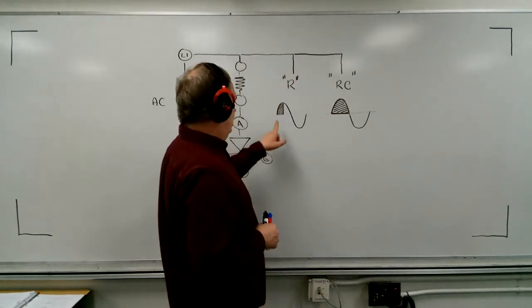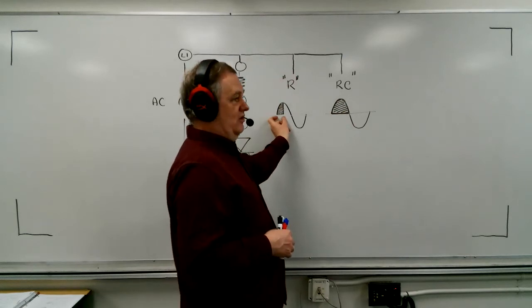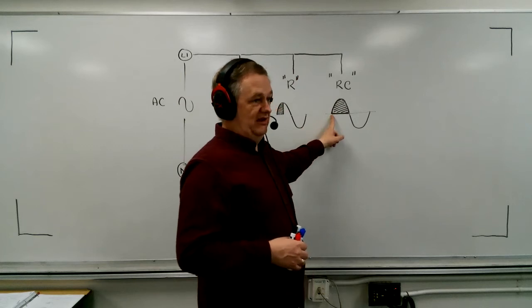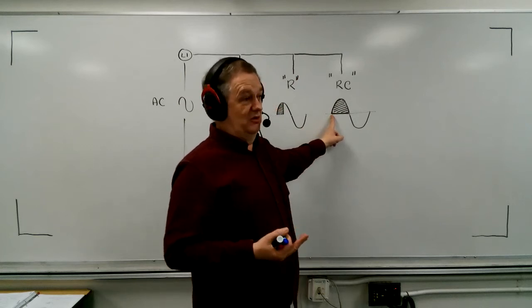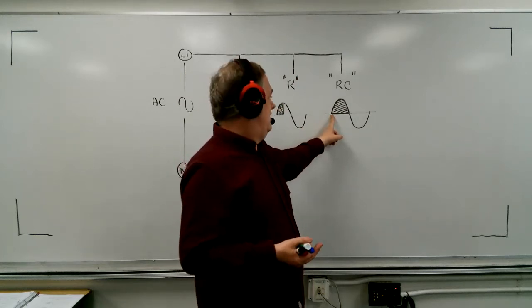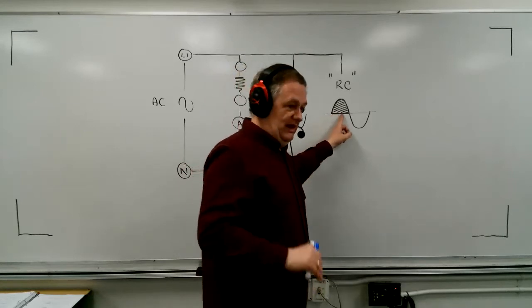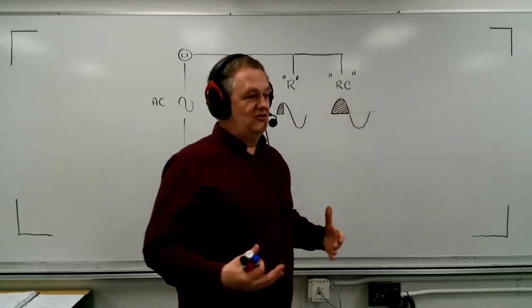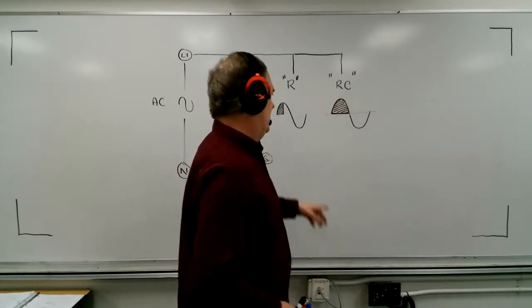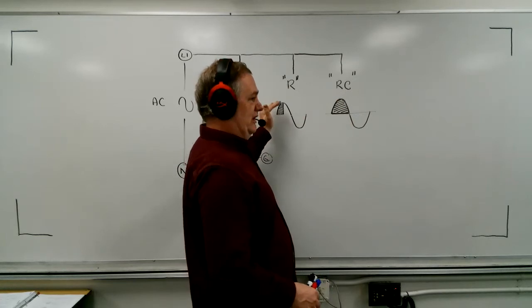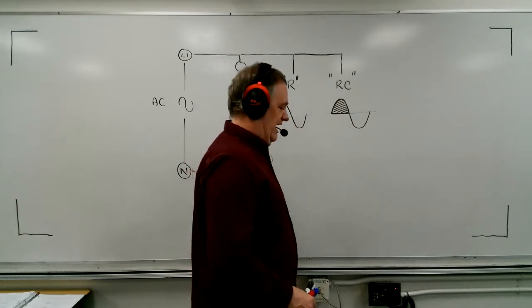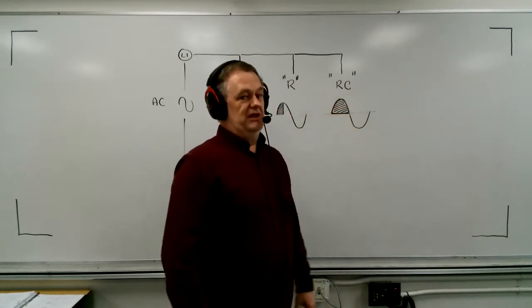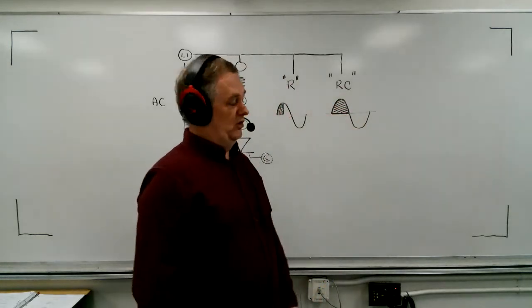And so this one here, you only have a little window of voltage control. This one, you can go from 45% of E line, which is your highest possible with a half wave rectifier, and you can fade that voltage all the way down to 0 volts. So RC circuits give you nicer, smoother control all the way to the end. This one, the voltage would go down, down, down, and then bang, just shut off. Whereas this one is going to fade all the way down until it's out at 0 volts, okay?